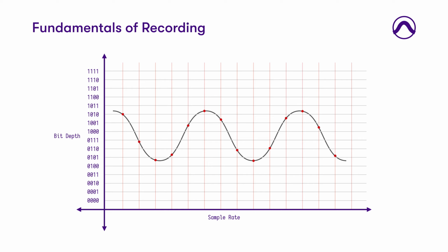If we look closely, many of these dots do not correspond exactly to our bits, which means the samples will be assigned the binary number that is closest to it, and that is what the computer gets. The computer will redraw the waveform in our digital audio workstation based on these samples. And because of the lack of proper information, the waveform that it recreates is quite different from what we actually had. This is our original waveform, and this is what the computer has recorded. We can see how different both of these are.